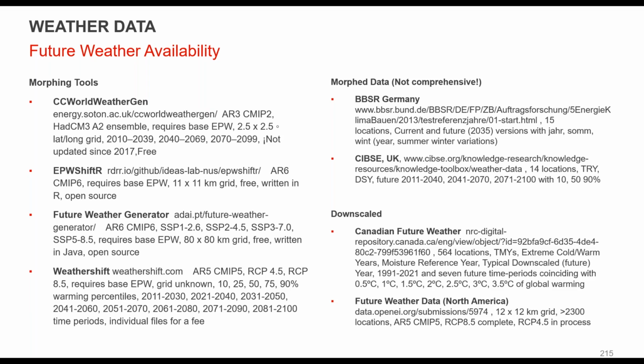Jose also asked, for places that have a lot of stations, what would be a good rule of thumb to use a radius applicable to the station? I would look at elevation change. I'd look at proximity to water to make sure that they're similar. If your building or project is on the coast, you want to find a location that is similar to that.